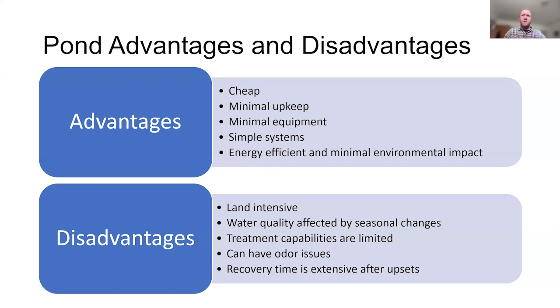The treatment capabilities can be limited. And this is generally true, but of course you can have lagoons with multiple cells in series. And so the treatment can be pretty good, but they're not going to get you to quite the level of a mechanical plant. They can have odor issues, and that is because you're going to have these big lakes full of sewage that is being treated. Although depending on how you're operating and managing that, you can really reduce the odors.